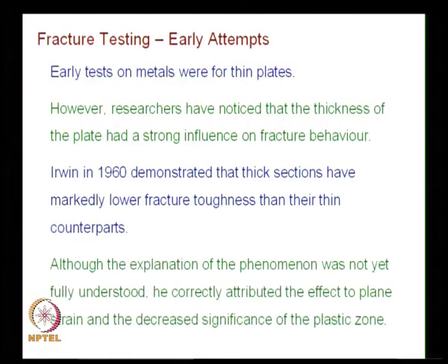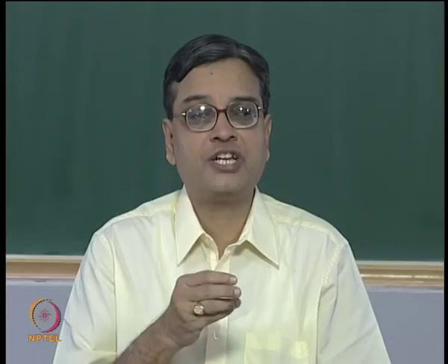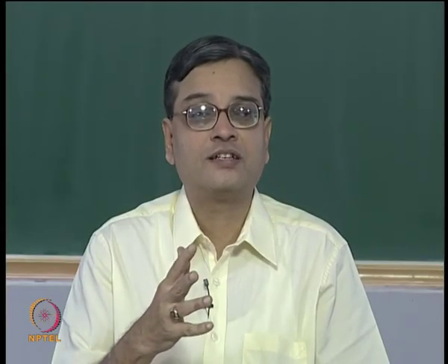And this is also recorded that earlier there was no explanation of the phenomenon available. However, Irwin correctly attributed the effect to plane strain and the decreased significance of the plastic zone. See, in the earlier discussion I had mentioned plastic zone is a friend for fracture mechanics, that is what I said.